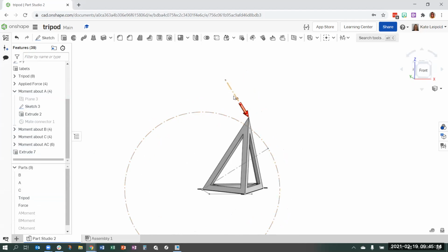I have a line drawn representing the force. Forces are not in inches or millimeters, but I have established the line length based on what the overall magnitude of the force would be. I used Onshape to physically create this vector in 3D space. So going from point D, I traveled backwards the X, the Y, and the Z locations. So this length here represents my force in relative scale.